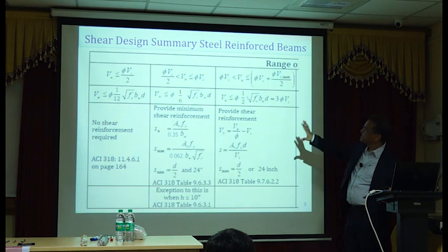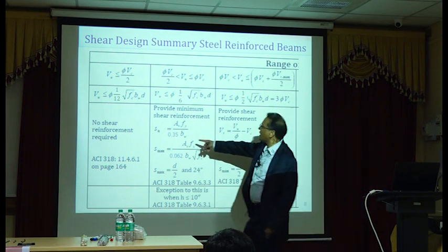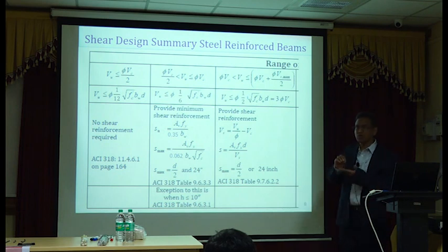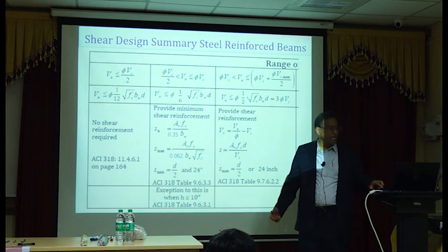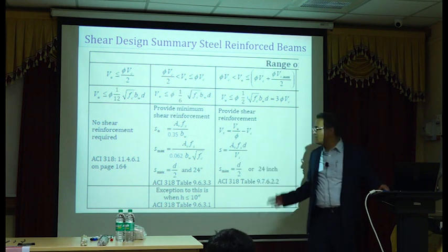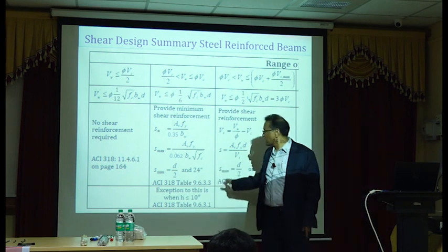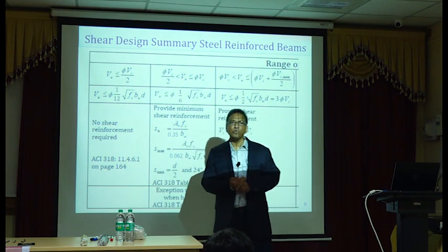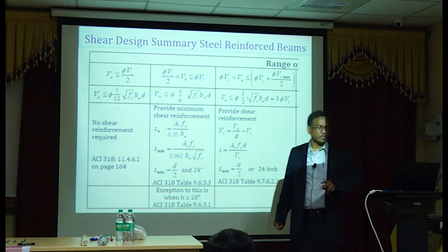So I have a slightly enlarged version of the one slide, and this time I have everything in SI units. So these 3 slides with SI units, in case you want to get a feel for numbers, you want to compare the numbers with your IS 456 design equations, you can do that and see where it stands. And of course, some of these spacing requirements have been changed in the last 10-15 years. I don't know how many of you are able to get into IS 456 committees. It's very hard to get into those big ones.